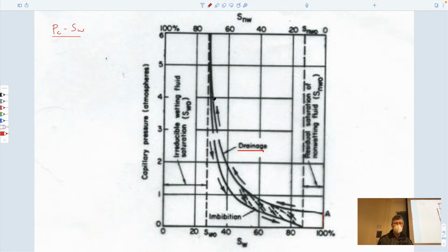It's saying that no matter how you try to push more air into it, you can't get the last bit of water out of it. And that's because you have this pendular saturation. You can get it out of the big open pores, but when you get down to very low saturations, you have grain on grain, you have a monolayer covering of water on the grains, and you have this pendular ring at the contacts, which has a very tight radius of curvature, and it means it doesn't come out very easily at all. And so you end up with this asymptote, and this asymptote is important because it's referred to as